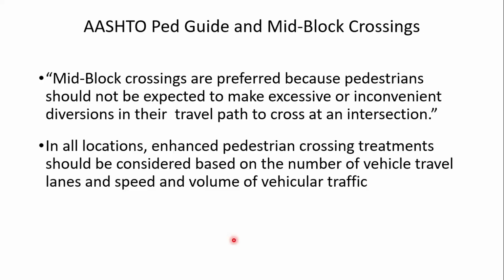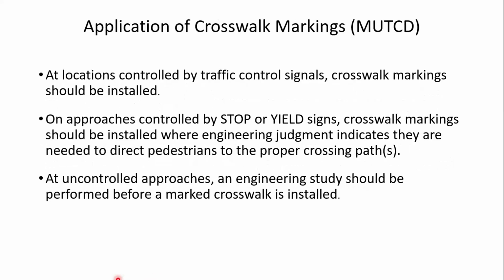The AASHTO pedestrian guide addresses mid-block crossings and has some advice. They say mid-block crossings are preferred because pedestrians should not be expected to make excessive or inconvenient diversions in their travel path to cross at an intersection. But in all locations, enhanced pedestrian crossing treatments should be considered based on the number of vehicle travel lanes and the speed and volume of traffic. So they recommend enhanced crossing treatments, which we'll look at.